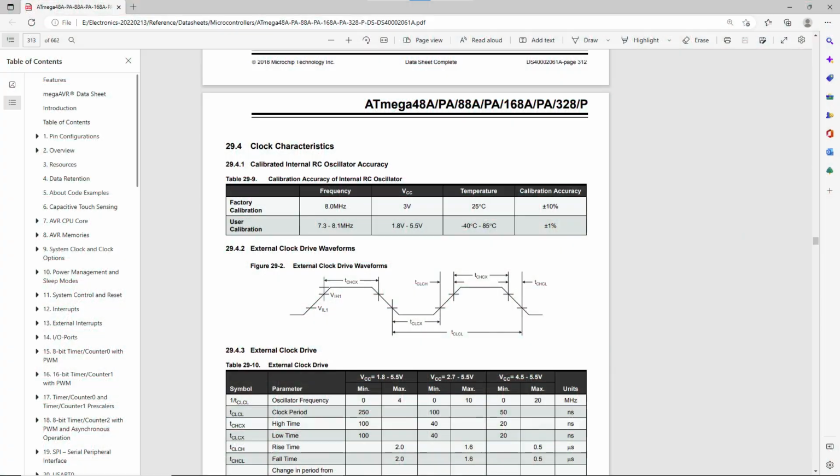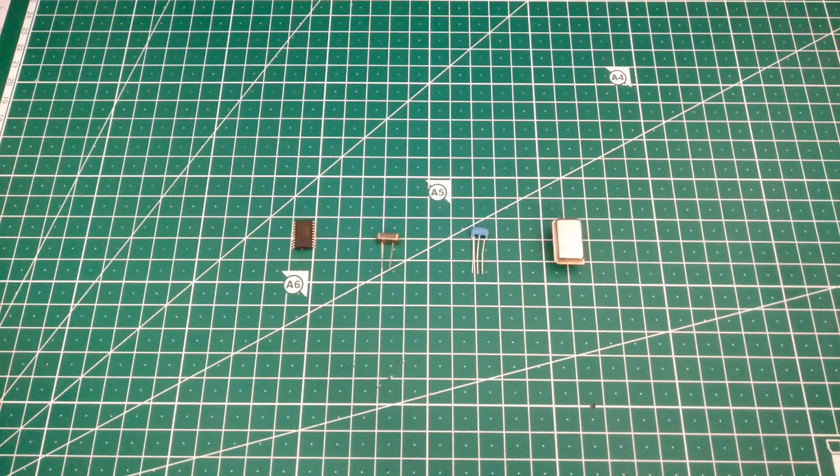Specifically, there's a high degree of error to the frequency it produces, which can be off by as much as 10%. And even in good microcontrollers with good internal oscillators, it will still be off by 2–3%. Further, it drifts with temperature. So that means that in your circuit, with exactly the same chip, it can be running at one speed when it's warmer and at a different speed when it's colder.